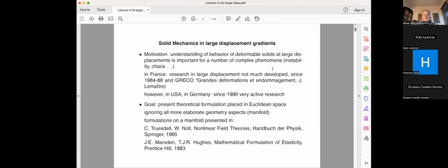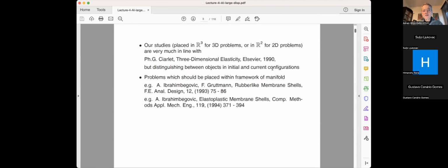In fact, there was the thesis of a person I won't name, who was working with Ray Clough. It was one of the last theses on shells that Ray Clough was coaching at Berkeley. It was developing a general shell element in curvilinear coordinates. At the end, the main result was just to make a finite element approximation which can represent the rigid body modes. Really, it was not a big success because the locking phenomenon was so severe that you could not really handle it. But hopefully, as we go along, we'll mention other types of approaches, and you'll see that you can do much better today.